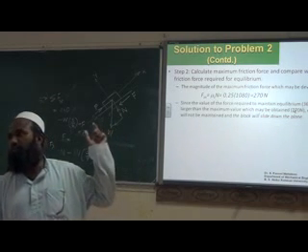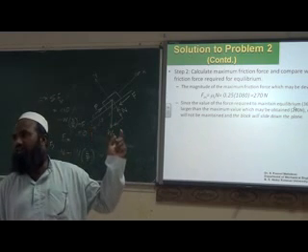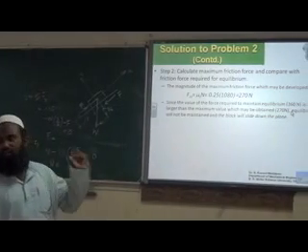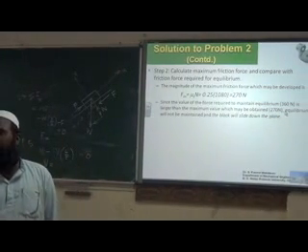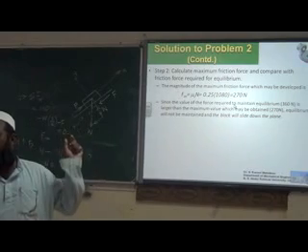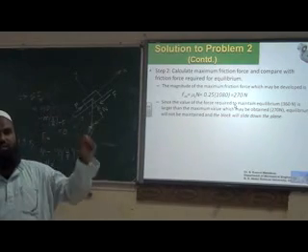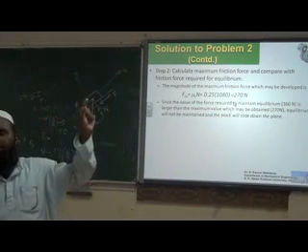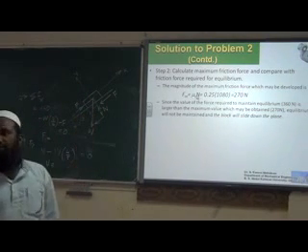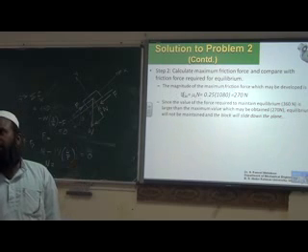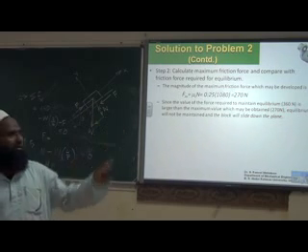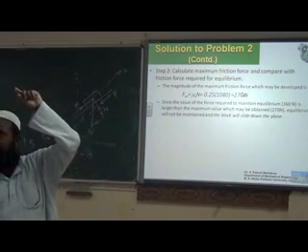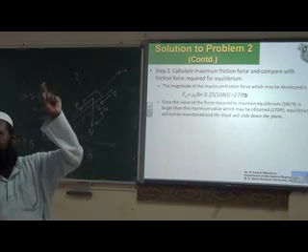Actually, the force required to keep the equilibrium is 360 Newton, but the maximum force is 270 Newton only. So there is no equilibrium. Equilibrium cannot be obtained. Actual frictional force, considering the coefficient of friction, is 270 only. It is given mu as 0.25. Considering the coefficient of friction, the maximum frictional force we can have is 270 Newton only, whereas from the previous slide we have found the equilibrium force is 360.